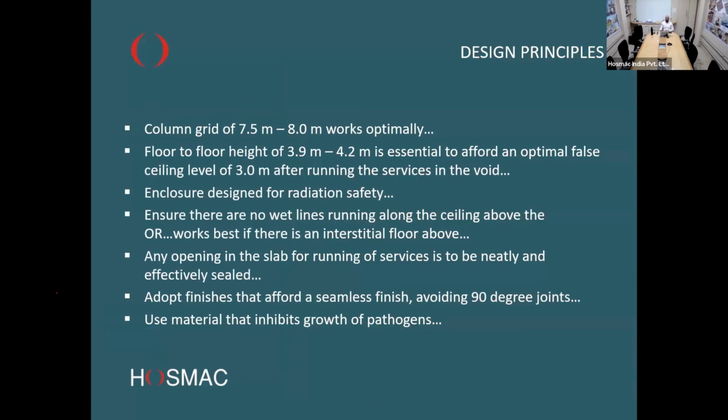Coming back to design principles, this is where we're stepping back a little to see what kind of column grid or spans work well. While there have been instances where we worked with 7.5 to 8 meters, we are increasingly moving towards adopting a grid of 8.5 to 9 meters, which works even better.